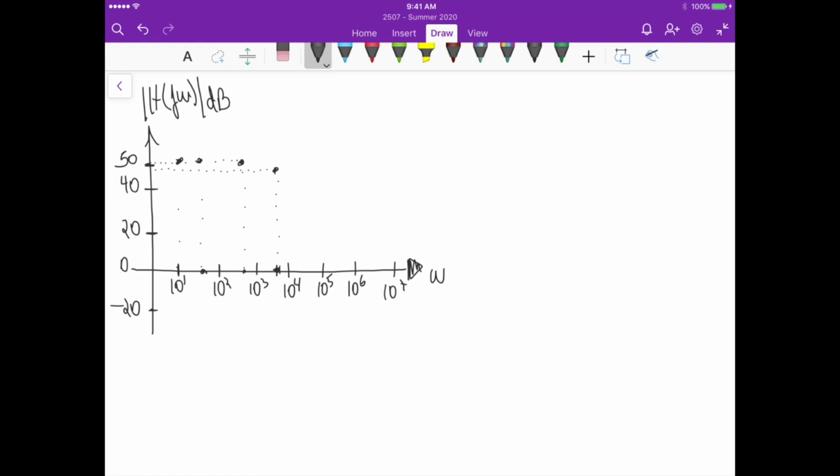Okay, now we also have calculated the unity gain, right? The unity gain frequency we calculated is around 1.25 mega radians per second. So 1 mega is exactly here. Now 1.25 is almost here.